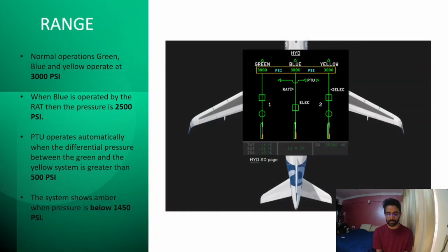Alright. So in normal cases, your hydraulic pressure is always measured in PSI, right? This pressure is 3000 psi, which is the normal operating pressure for a hydraulic system. If you remember in your SOPs, in your top of line checks, you check each system, right? So you need to know that this is your normal operating pressure. If it is less than 3000, say 2700, you need to ask why it is a little bit less. Or why is it a little bit too much?